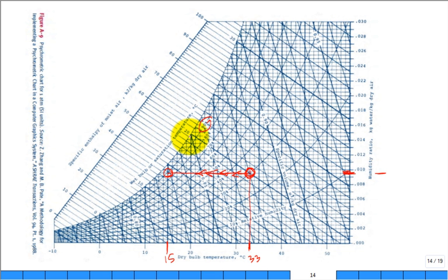Did any liquid or water turn into liquid? Did any vapor condense? No. Let's say somebody changes it up and says you cool it to 8 degrees C. Well, you're going to get all the way to 100. You'll hit the dew point. The dew point looks like it's around 13 degrees C for that condition.